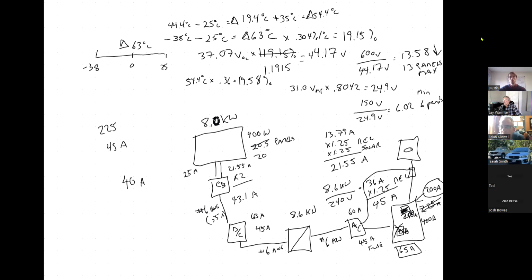You'd still have to have the power company disconnect, right? Oh, for sure, if you're wiring into an existing system. You're going to have an electrician come and cut the wire somewhere and put a junction box in here with a bus bar connection type port and all of that. So supply side connections are even more expensive than just swapping out the breaker.